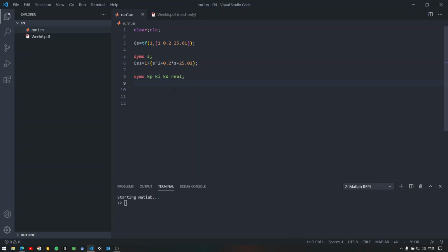The reason was that if you use kp, ki, and kd, you will get a polynomial that is linear in its coefficients, and that might help out in most cases because it's easier to process the information in front of you, and you can always go back and look at the zeros that are in our controller structure.